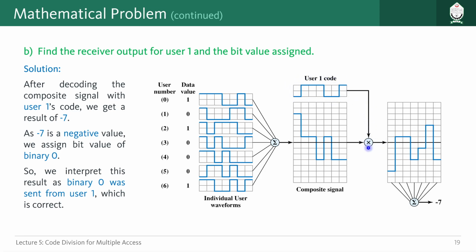Then we have to do the correlation, simple correlation, that will result in a waveform like this. Again, I am repeating that the reference value here is 0, and these are positive values and these are negative values, and all of these small squares represent a value of 1 vertically and also 1 horizontally. So obviously from that you can take these two waveforms and multiply them to get this waveform, and then finally we have to sum up the waveform.